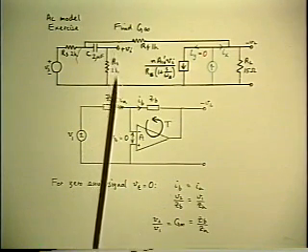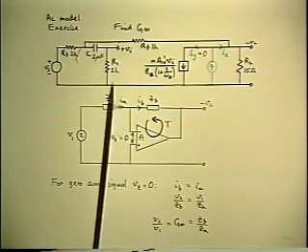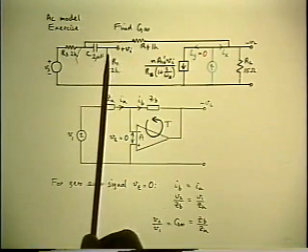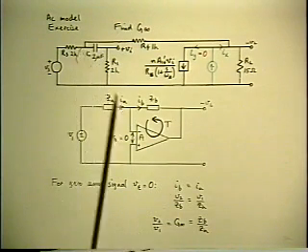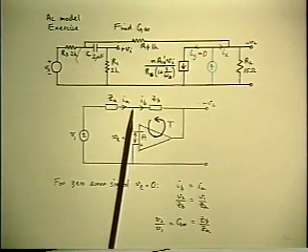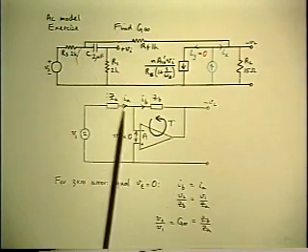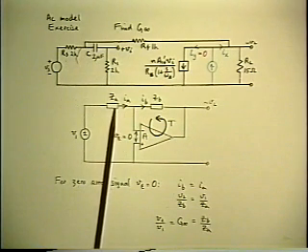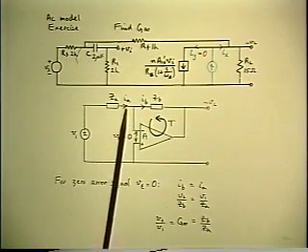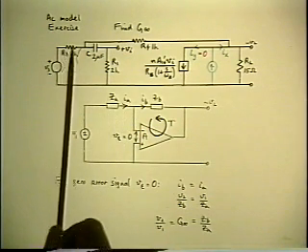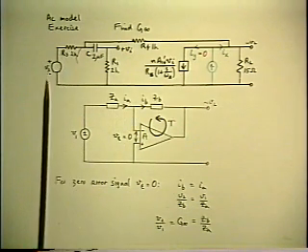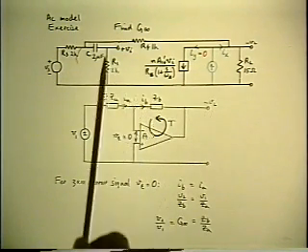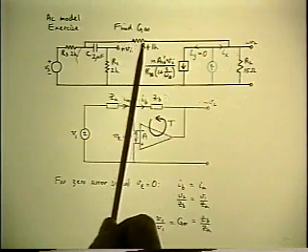You got 0 voltage across a 2K resistor, but you still get 0 current in the resistor, therefore 0 current in the capacitor as well. So the feedback summing point is equivalent to the same summing point here, and it is a virtual ground. And so the RS is equivalent to the ZA. So the IA current, which is V1 over ZA, is the same as VS over RS. And the V2 over ZB, which is the IB current, is equivalent to VL over RF.